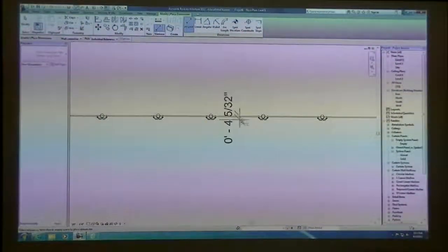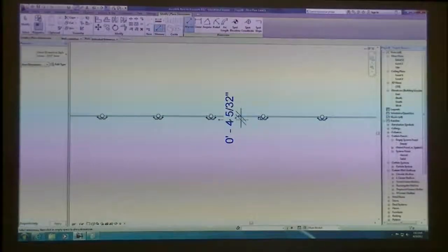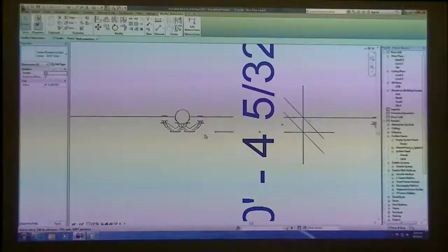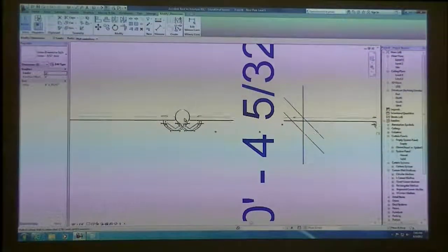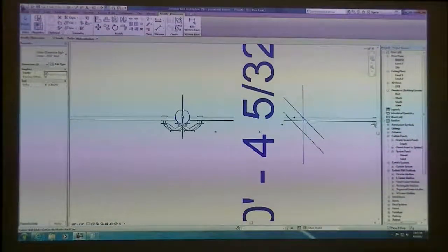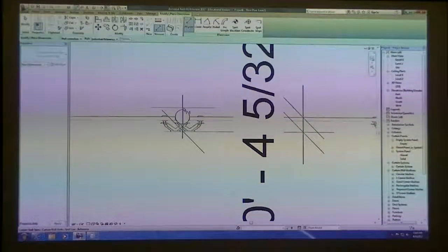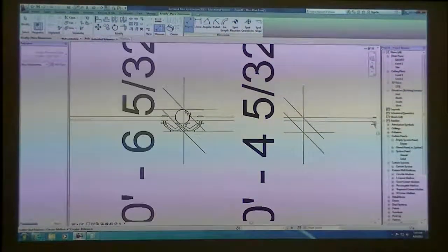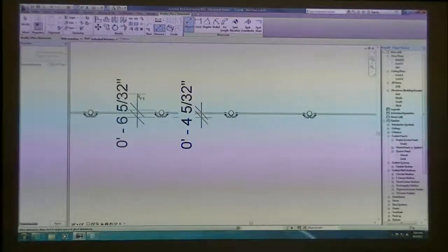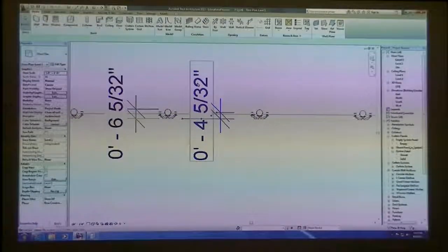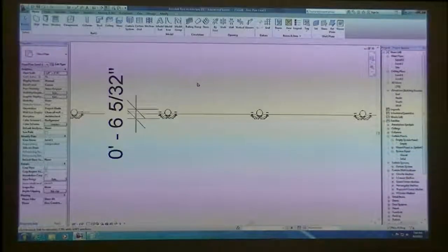So I'm going to measure, actually, to the center line measurement from the back face of the spider clip to the center of, I wonder if we can do to the edge of the circle. Yeah. We can do to the back edge of the circle is 6 and 5/32.